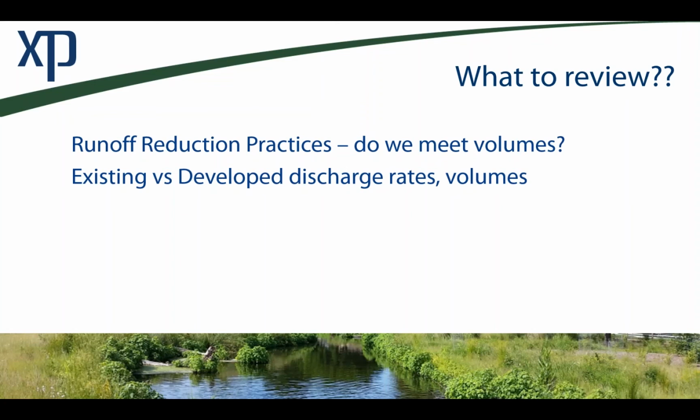Of course, there's a whole range of other rainfall events which will take place. So we're going to look at perhaps what we might call the protection events, the 2 through 100 year overbank, channel, and flooding protection events. And we're going to look at those versus, of course, the existing conditions.